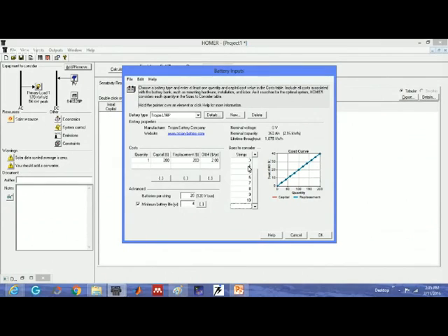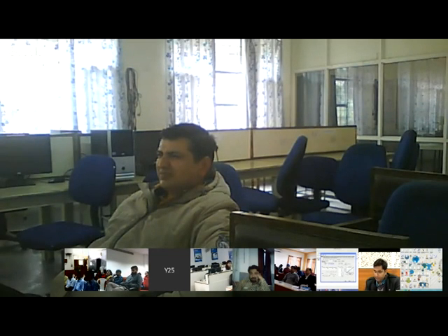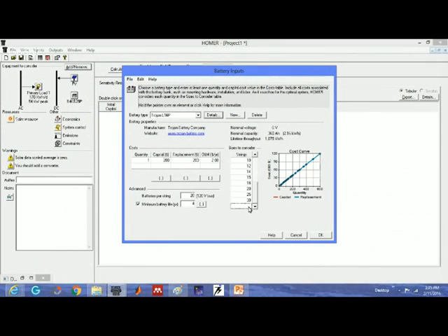Yes, any doubt is there? Okay. So number of batteries we can increase. Let's say 12, 14, 15, 18, 20, 25, 300, whatever the maximum. Let's say you want to fix the number of batteries, right? Let's say I can have maximum 300 batteries. I want to keep batteries minimum. So if you want to keep batteries minimum, you have to go voltage limit high, plus you need more, say PV installed capacity will be increased, or you need to put backup. And suppose you want only PV and battery only, then a limit will be there.